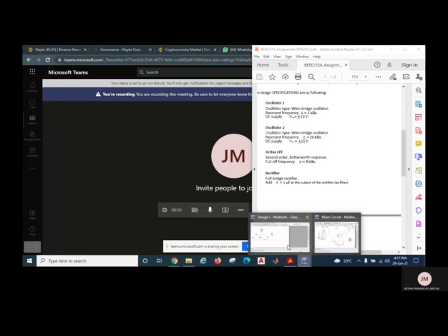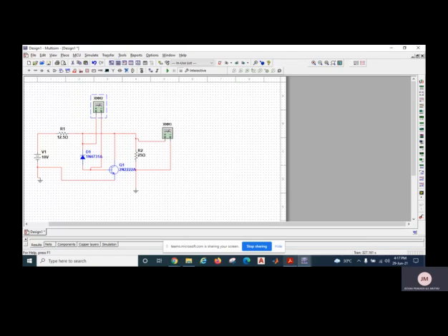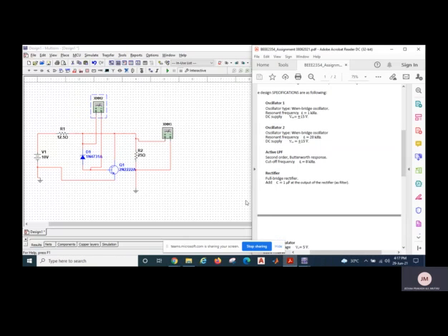I'm here to present my part, which is the voltage regulator. This is one of the circuits that my teammates helped me to conduct, a circuit about a voltage regulator, and I have used a shunt voltage regulator. A shunt voltage regulator usually works by providing a path from a supply voltage to the ground through a variable resistance. The current through a shunt regulator is driven away from the load and flows uselessly to the ground, making this form usually less efficient than the series regulator.